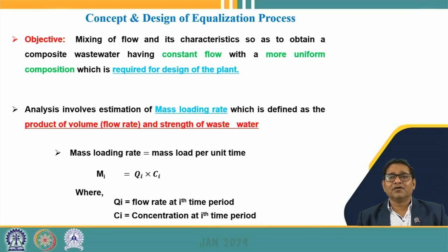As the name indicates, an equalization tank is a tank which equalizes the flow and the characteristics of the wastewater coming from different sources at different time durations, so as to obtain a constant flow and a more uniform composition of the wastewater, which is basically required for the design of the plant.